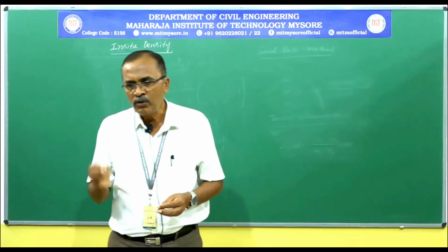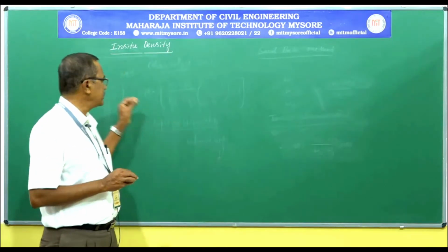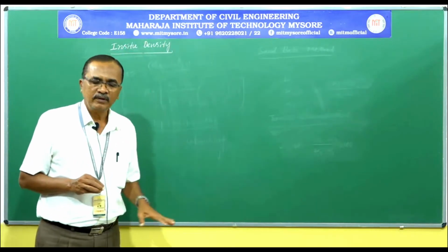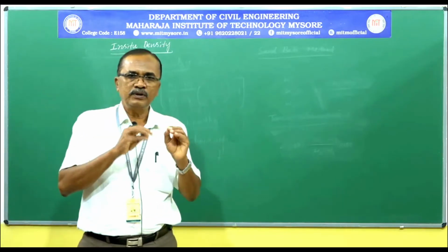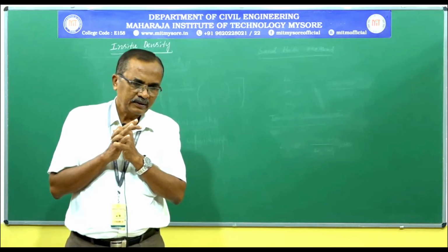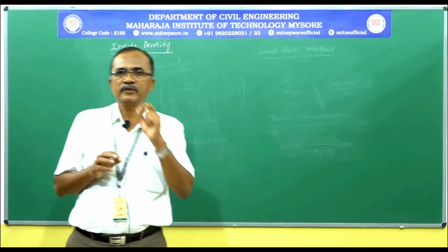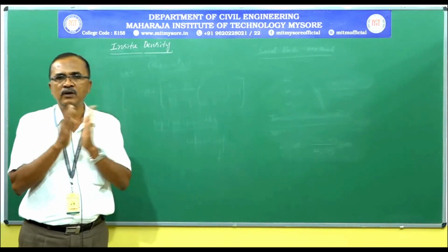The first and foremost test to be conducted when we visit the proposed site is in situ density. Again, that is in situ, in the site, knowing the denseness of the soil. What is the use of this in situ density? The purpose of determining in situ density is to know the denseness or looseness of the soil.